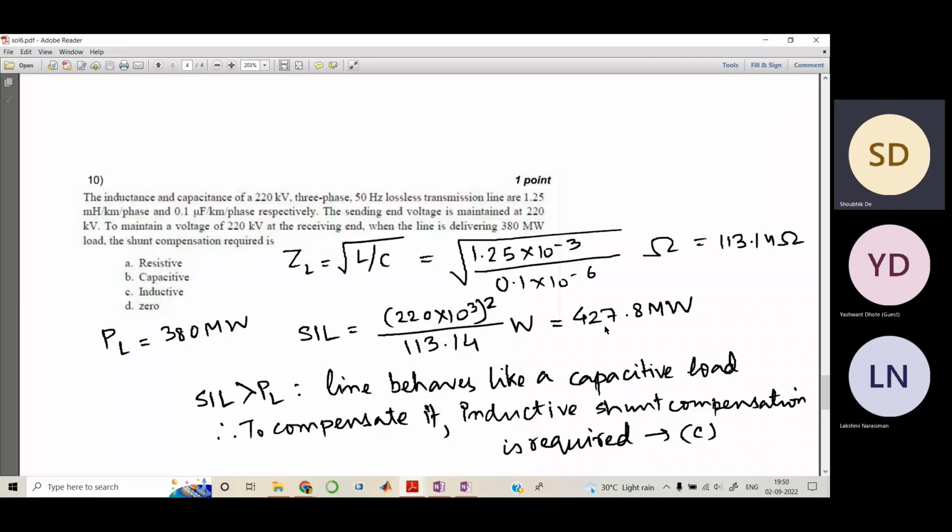As far as I know, your long transmission lines are basically distributed parameters, right? So for solving that, you need lumped parameters. You have to consider small sections of that line. We can also consider a T model, because the pi model and T model are both pretty standard. We can consider the T model as well while solving this kind of problem.